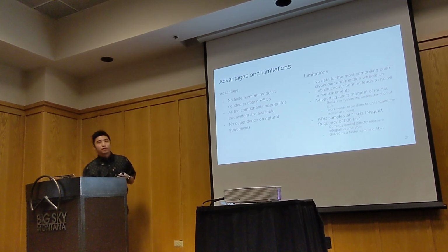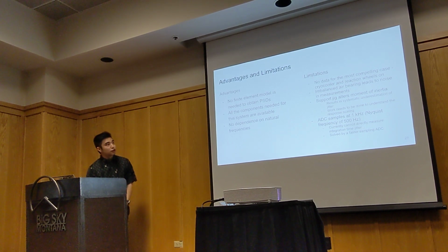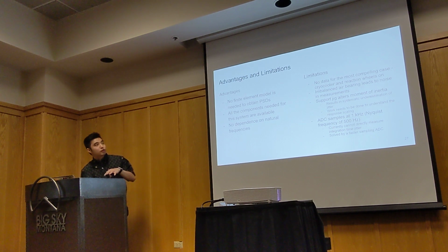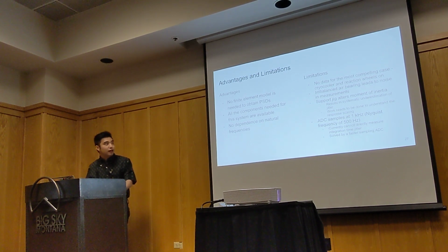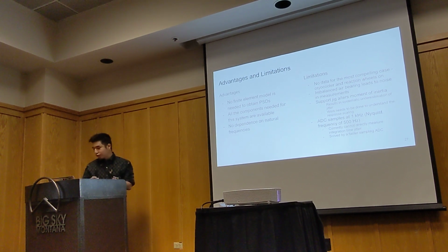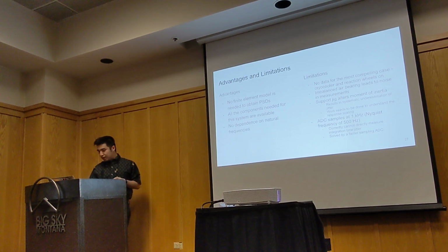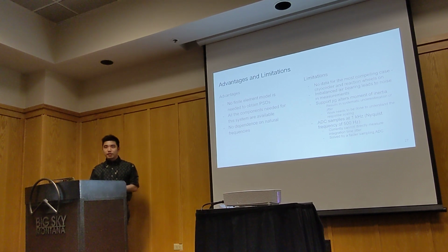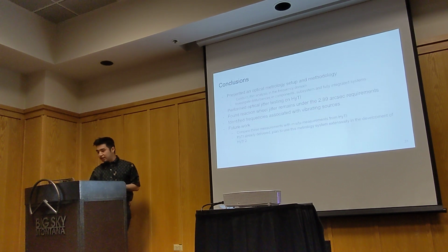Imbalance in the air bearing led to some noise in those measurements, as you saw those ghost spikes at 120 hertz. The support jig that you use alters the moment of inertia. It adds about 30% of HyTI's mass, in that bottom direction. And so we have to really work on trying to understand the response scaling for that. And in my opinion, the biggest limitation is the ADC: we have a really slow ADC that only samples at 1 kilohertz, but this is readily solved by just purchasing a faster ADC.